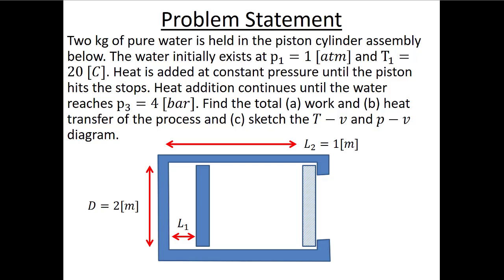What happens is you heat up the water and the oats that are in there, and the water gets hotter and hotter, but eventually it starts to form water vapor. And then as that happens, the increase in pressure in the vessel clicks this valve closed. Then you start to add heat and you get this higher pressure, right? And we know that that changes the saturation temperature of water. The boiling temperature of water goes up as the pressure goes up. So that's what's going to happen here.